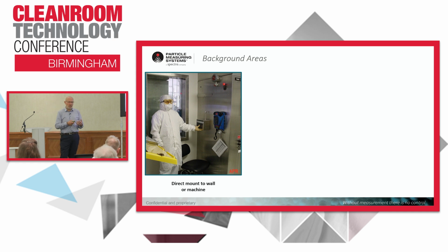And again, a big thing is that we need to get services. Some just need a single cable for power and data, and that can have a built-in pump. Sometimes we need vacuum tubing to it. We may need power, vacuum tubing, and data connections to a particle counter. So depending on what you're using, that has some bearing on locations, but that's an example directly mounted to a wall, and going directly into it.